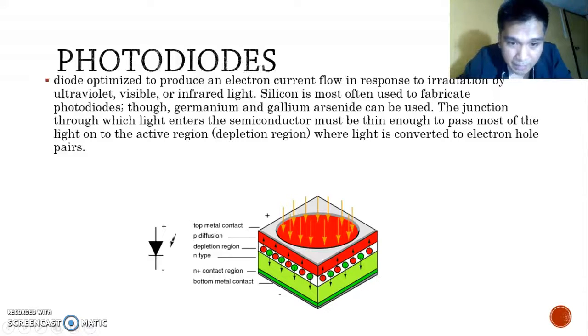A shallow P-type diffusion into an N-type wafer produces a PN junction near the surface of the wafer. The P-type layer needs to be thin to pass as much light as possible. A heavy N+ diffusion on the back of the wafer makes contact with metallization. The top metallization may be a fine grid of metallic fingers on the top of the wafer for large cells. In small photodiodes, the top contact might be a single bond wire contacting the bare P-type silicon top.